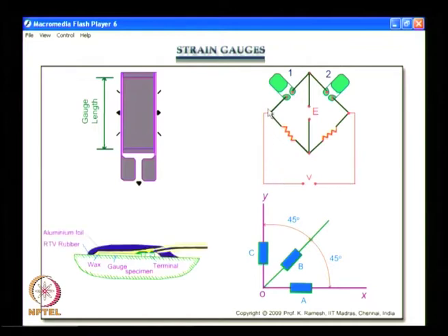Here I have a Wheatstone bridge shown, and this also has two strain gauges connected, in a half bridge configuration. In fact, this is a most celebrated one because it also has temperature compensation provided when these two strain gauges are representing the point at the model of interest, and the one which is also kept at the same temperature. So that any temperature effect happening at the specimen is compensated by the second strain gauge.